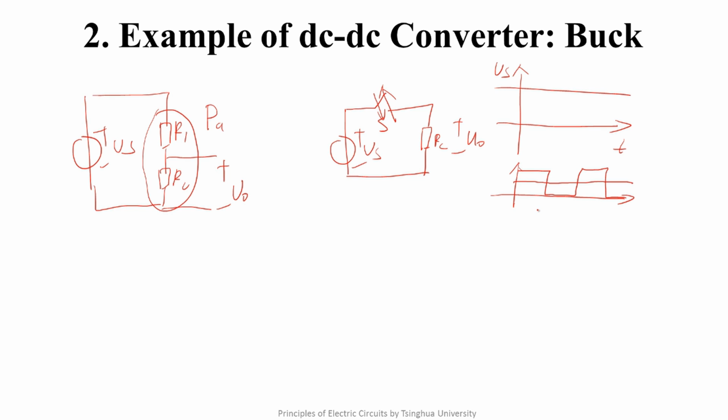The previous smoothing capacitor realized a function of keeping the voltage in a short time. Can we take advantage of the inductor to keep the current in a short time with such a circuit? If the inductor has a large value, which keeps the current flowing through RL when the switch is open, then the load voltage is kept constant. Is this design practical?